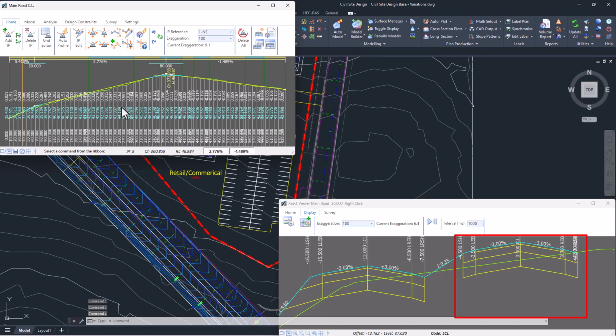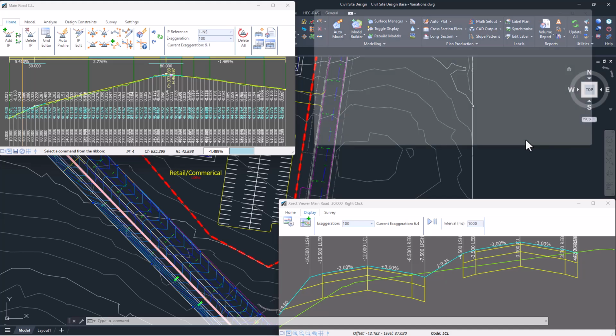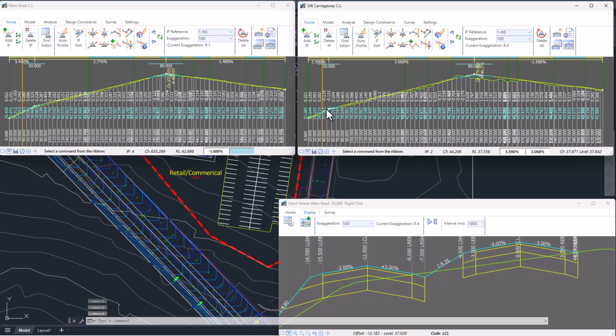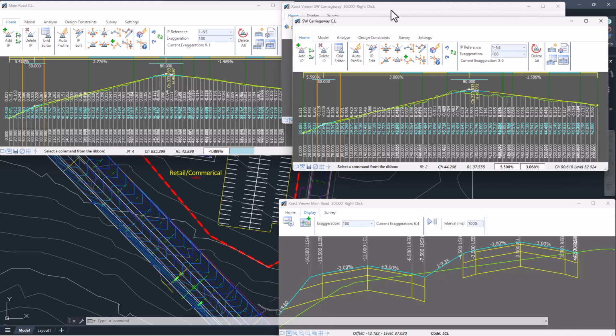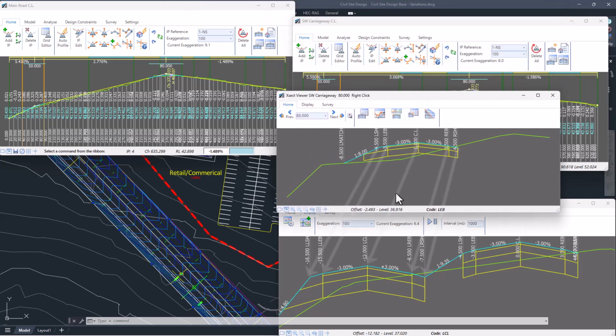And if we look at the other string, so we do have our other string here for what is the left side, that string has its own cross-section design, and what we are doing is already running a variation where we're tracking the cross-section of this string and tracing it onto the cross-sections of what is the right hand side or the main alignment that we're working with.